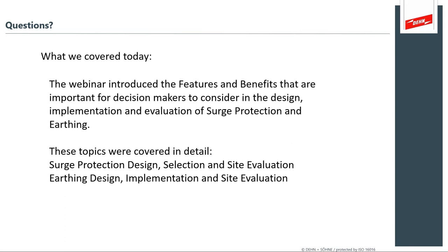Well, this is really a great portion of the IEC methods, because IEC pays a lot of attention to the direct strike energy that's associated with lightning. The NFPA and UL methods, although they're very thorough, don't have some of the same testing of direct strike lightning energy on SPD devices.